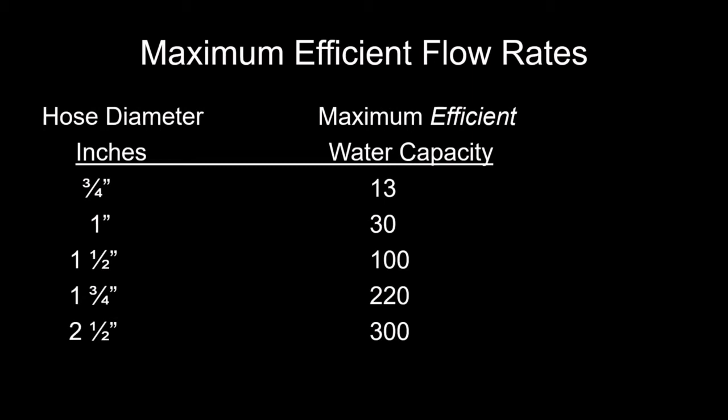But it's not like we have that laying around. And then 2.5 being capped at about 300 gallons a minute, I think that's pertinent because if I'm running some of our big Type 3s and I'm plugged into a hydrant and that boosts my performance a little bit, and I'm moving 300 gallons a minute, I have seen it where I've collapsed a soft suction line because we were moving more than 300 gallons a minute out the discharge deck gun of a Type 3 engine. So recognize those limitations.